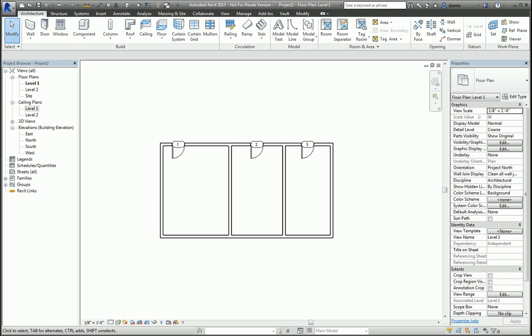In today's screencast, we'll be taking a look at the floor command in Revit. Here I am in Revit in a default architectural project. I've got some walls and doors already created. If I go to the Architecture tab of the ribbon Build panel, I can click the Floor command. I can choose to create an architectural floor, a structural floor which has structural data such as analytical information, and floor by face. This screencast will cover architectural floors.